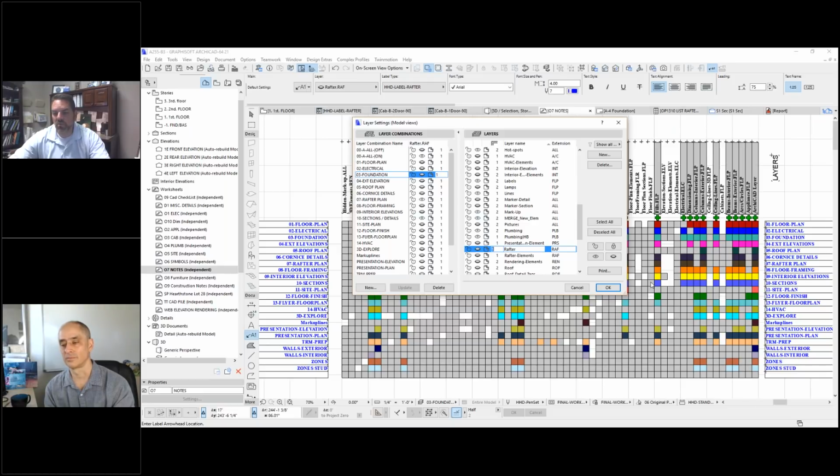So some of your cabinets may reflect a version 18, but then you start adding new cabinets to the working drawing. So then you start using 21 version cabinets. Well, some of them are going to be referencing the new layer. Then you still have some old layer systems coming in. So now you need to get those layer combinations to where they're both showing. And this is just a quick way to see visually what's happening within the layers, the layer visual.